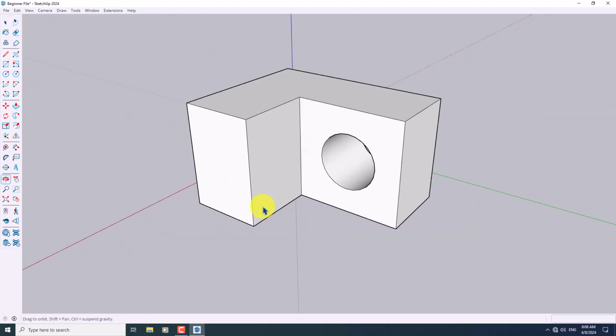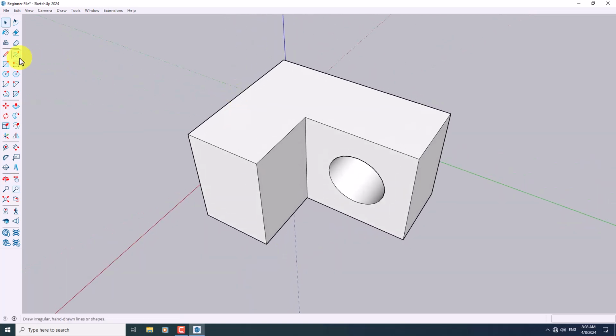You can do this job on different types of surfaces. For example, I can click on this line in here and draw some lines like that. Click on the circle another time and create another section for it. But this time I want to use polygons. Next to the circle we have the polygon option in here. If I click on the polygon, you can see we have sides, and it's about 6. It means that we have 6 sides. If I type 5 and press enter, now we will have a 5-sided design. So it works very simple and easy.